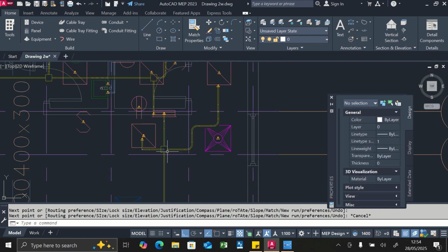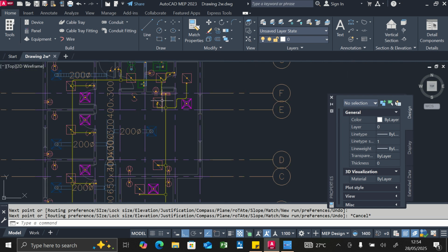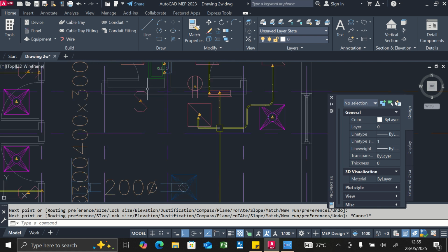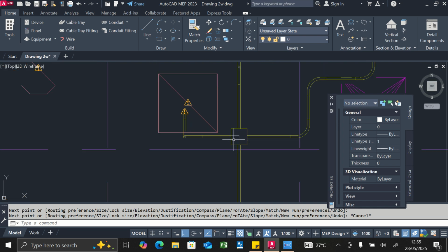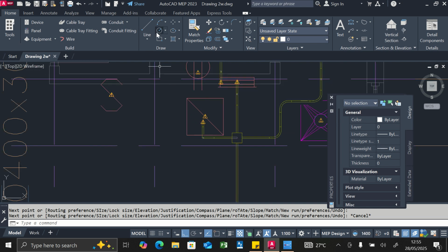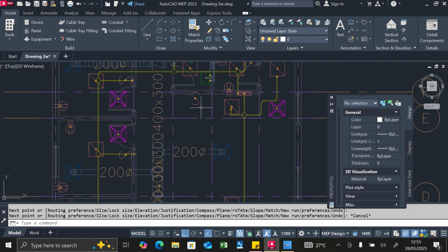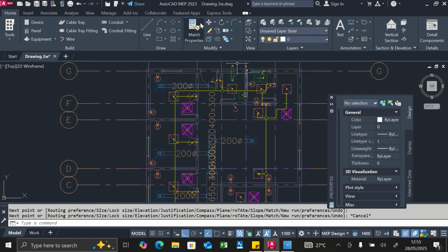All right. So you see that it automatically creates a junction box when you are trying to connect to it. So now we're able to connect all the lights. So let's connect to various switches. All right. So these particular lights, and all these three lights, are being controlled by one switch. Let's assume so. So we are going to, from this point, just take it all the way.